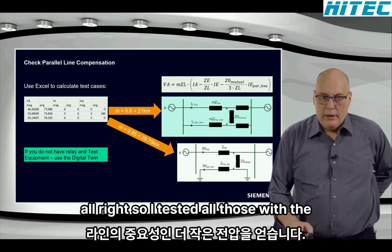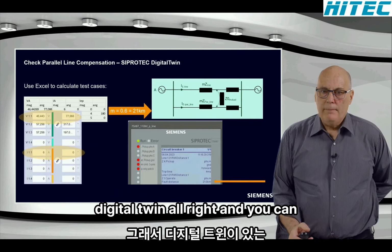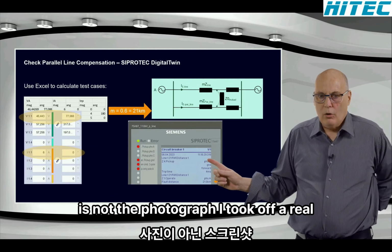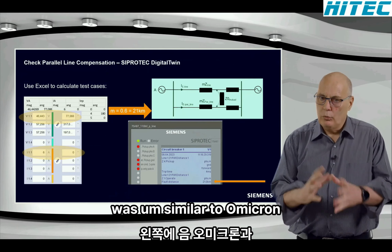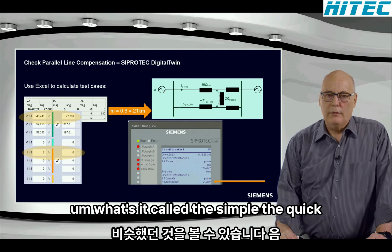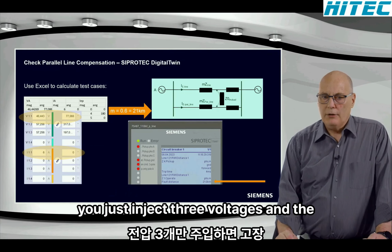All right, so I tested all those with the digital twin. You can see the screenshot. That is not a photograph I took of a real relay. That's a screenshot from the digital twin. On the left, you can see something similar to an Omicron, the quick CMC. You just inject 3 voltages and the fault current.